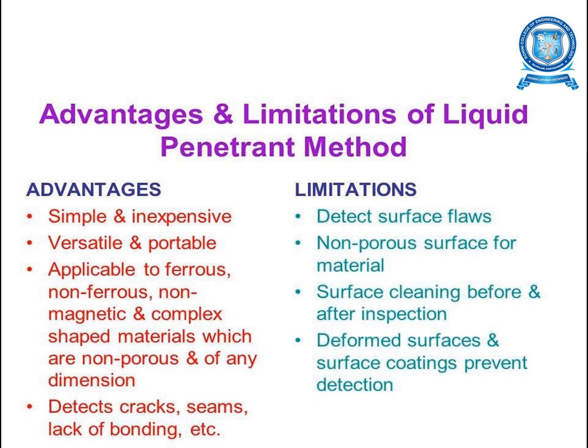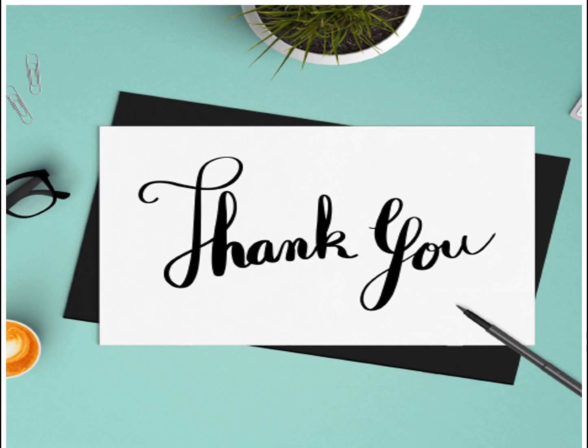Normally it is used to detect cracks, seams, lack of bonding, etc. And the limitations are: it detects only surface flaws, so the material needs a non-porous surface. Surface cleaning before and after inspection is required, and deformed surfaces and surface coatings prevent detection.